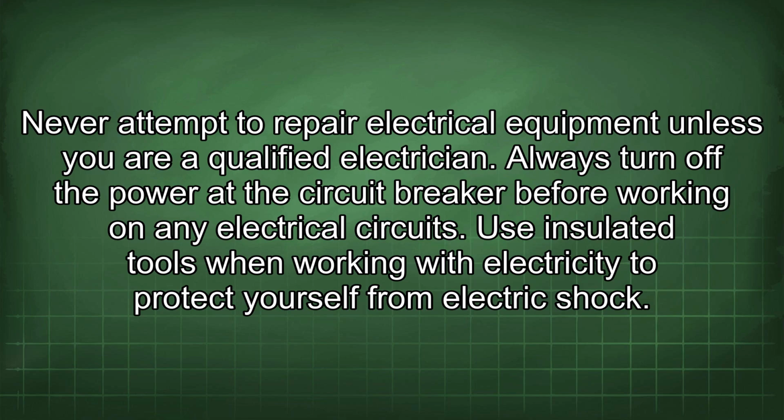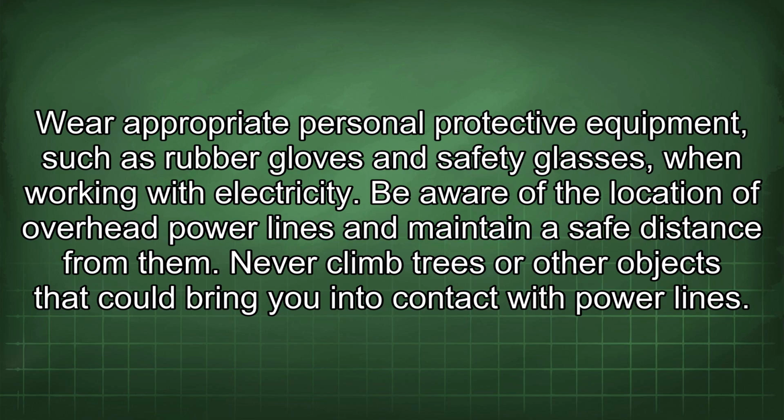Always turn off the power at the circuit breaker before working on any electrical circuits. Use insulated tools when working with electricity to protect yourself from electric shock. Wear appropriate personal protective equipment, such as rubber gloves and safety glasses, when working with electricity.